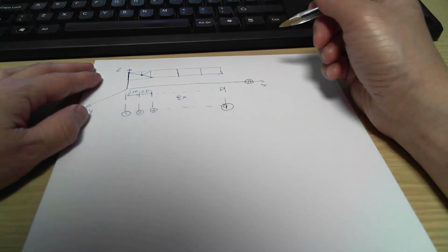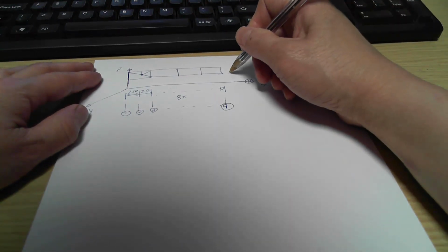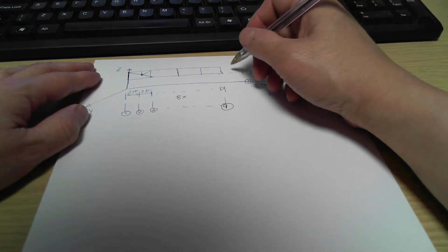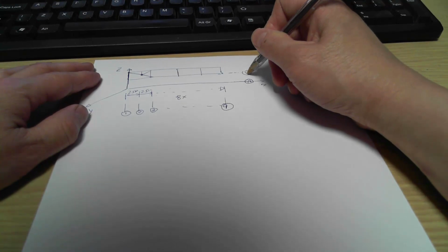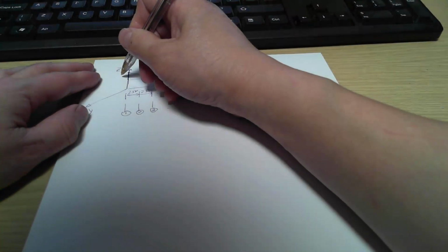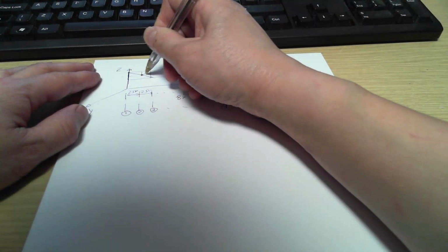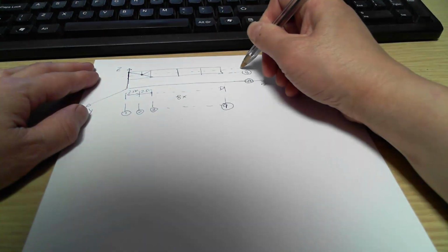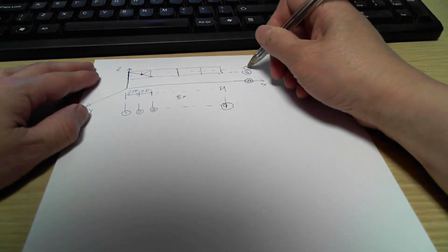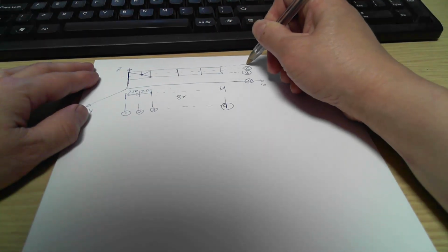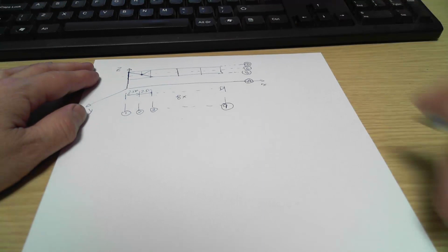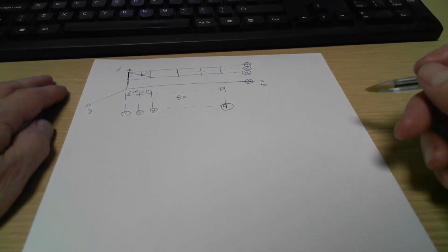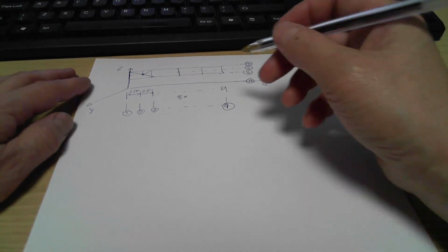So let's use A to represent that one, and then the second line is going to be the bottom chord of the truss, so that's going to be the B axis. The last one, because you want to snap into the middle point in here, you have another grid line, which is C in here, and the final line is 6 meters above the ground, that's the D. Okay, so this is the grid line we need to generate from the structures in here.